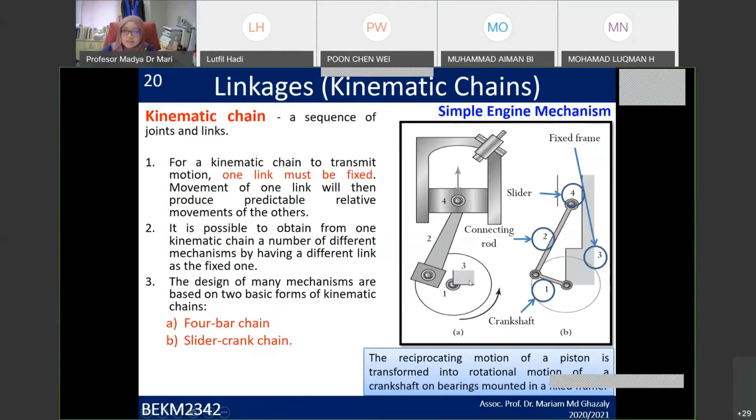Circle that. So the crankshaft is going to rotate across the shaft there. Because the crankshaft is connected to this link by a joint here, this joint, and the joint here is connected to the cylinder, what happens is that when this rotates, it's going to move the slider up and down. And if you see to the right side over here, how can the slider move up and down?